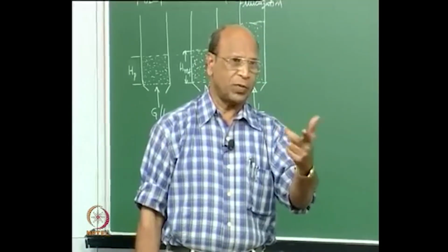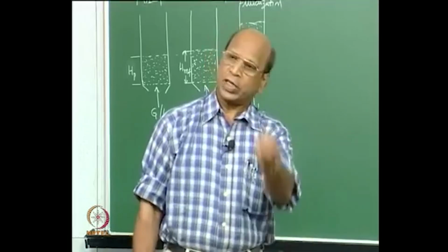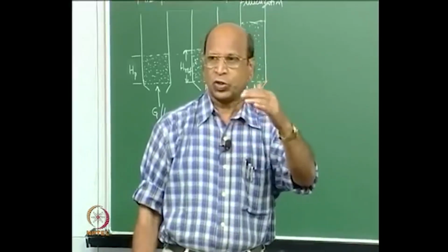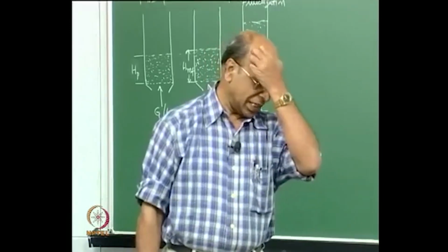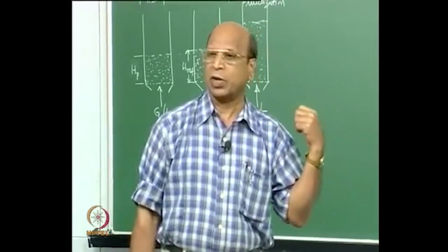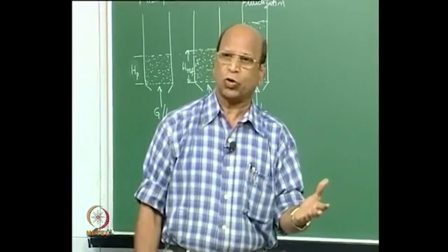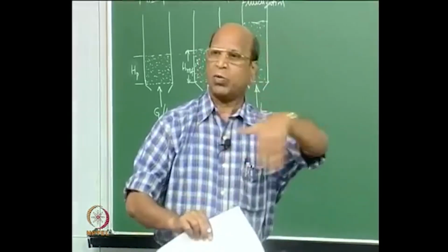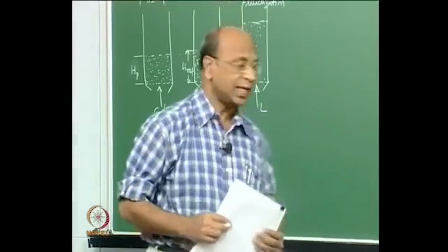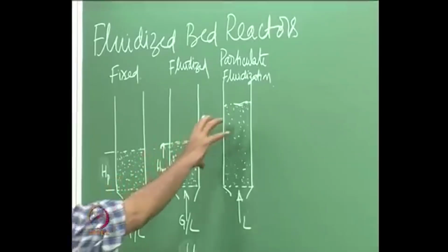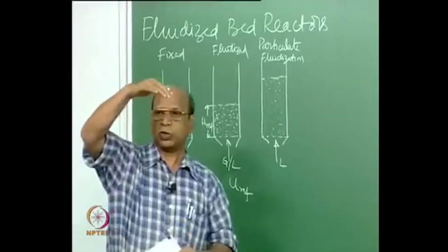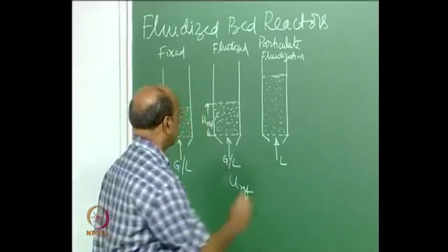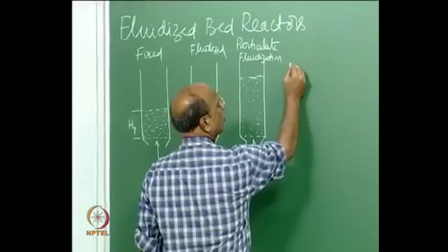So, keeping the weight same, and when you increase the drag force, by changing the liquid velocity or gas velocity, the pressure drop is not going to change, only thing is in the bed you will have different conditions coming. So, like that in the particulate fluidization condition, the pressure drop will not change, but the bed can be very smoothly varying. Now, the same situation if I show for gas,